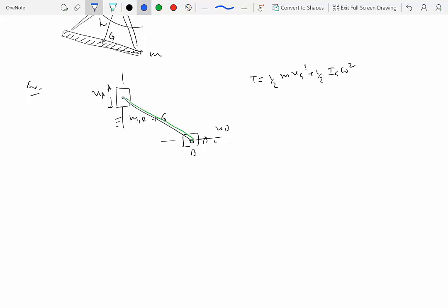You will recall from the discussion in module 6, kinematics of rigid bodies moving in a plane, we have to locate the velocity vector directions of at least two points on the same rigid body and then draw perpendiculars to those velocity vectors. Point B has a velocity vector that way, point A has that way, so we draw the perpendiculars to those velocity vectors going through points A and B, and this is where the instantaneous center is located at this instant.